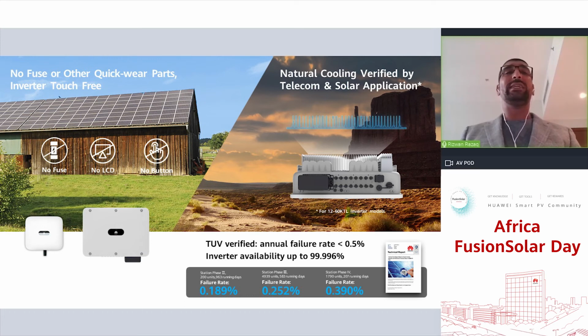So how do you physically commission the inverter itself? It's all done through your mobile phone. And as for the cooling of the inverter, as you can see on the top right hand side of the screen, the heatsink is clearly developed for where the high hot spotting is within the internal device of the product itself. So there is more surface area available for the cooling of that particular area of the inverter. And this is something that we've collaborated with TUV on for multiple different projects, where they've verified that the failure rate is less than 0.5% and an availability of up to 99.996% was achieved.